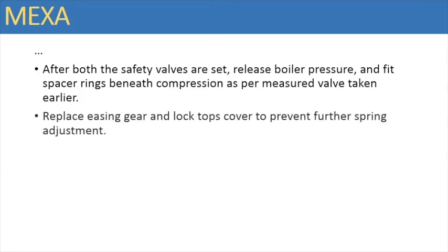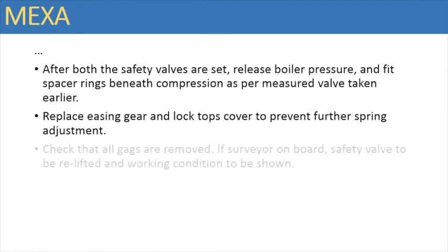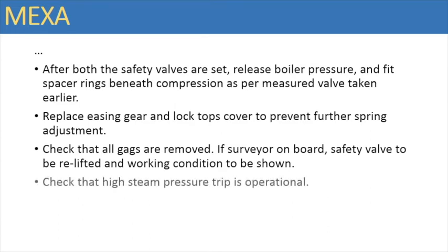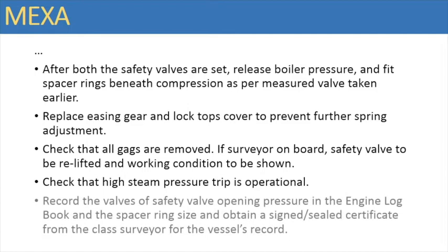If the surveyor is on board, the safety valve is to be relifted and working condition shown to him. Check that high steam pressure trip is operational and then record the values of safety valve opening pressure in the engine room logbook and the spacer ring size, and obtain a signed sealed certificate from the class surveyor for the vessel's record.